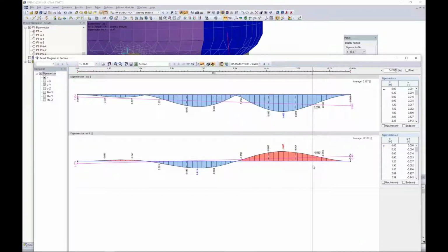So what we want to do here then is to model the imperfection, keeping this into consideration with these tolerances. And I also want to backtrack and just mention that the AISC 360 tells us that we should really model these imperfections directly. There are other alternative methods such as applying notional loads and such, but in some way or another they should be accounted for. So we're going to refer to the AISC Code of Standard Practice.